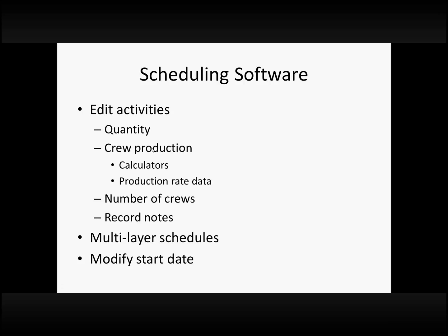So the scheduler can put in a number of crews, and also there's a provision just to type in notes so they can record what they thought about and why they made that decision. We did put in a couple of provisions for what I call multi-layer schedules, where we can break some activities down into more refined sub-activities, and at some point they can modify the start date if there's a change to that.